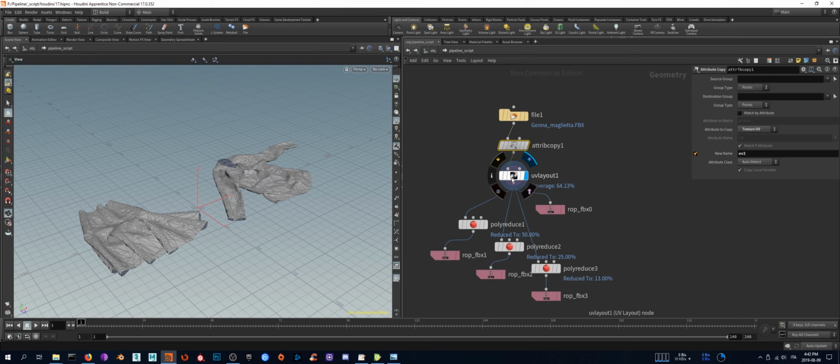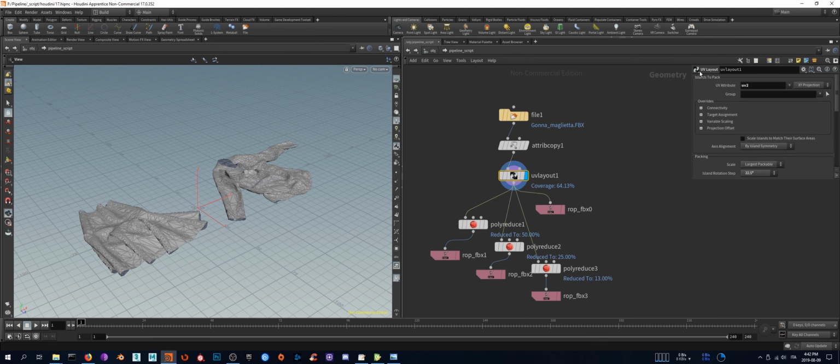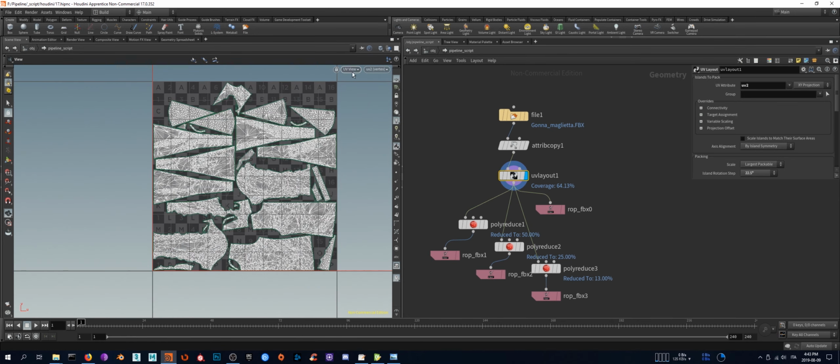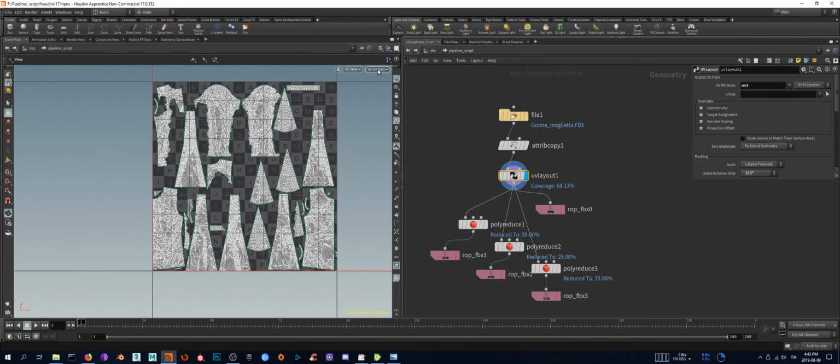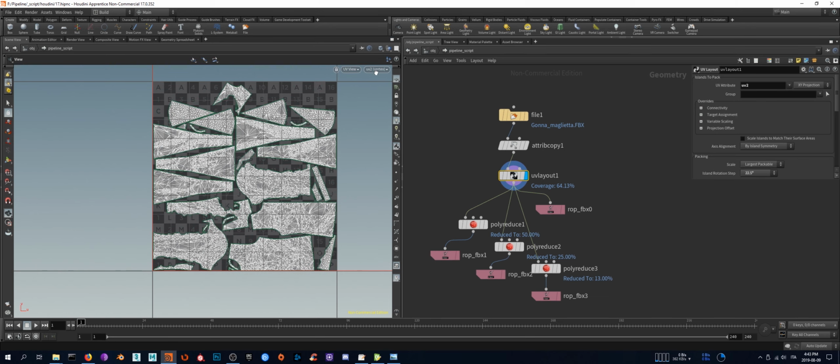The second thing is taking that channel and doing a UV layout, so as to redistribute the islands a bit better, to actually allow us to then use them for the light maps inside of Unreal. So as you can see, this is the first and original UV channel that comes with the object. This is the one that we actually generated now.